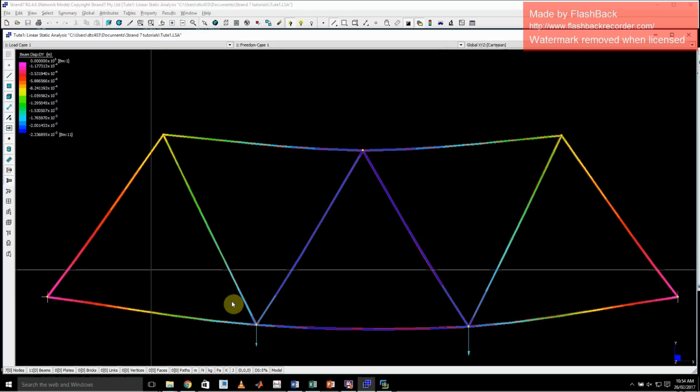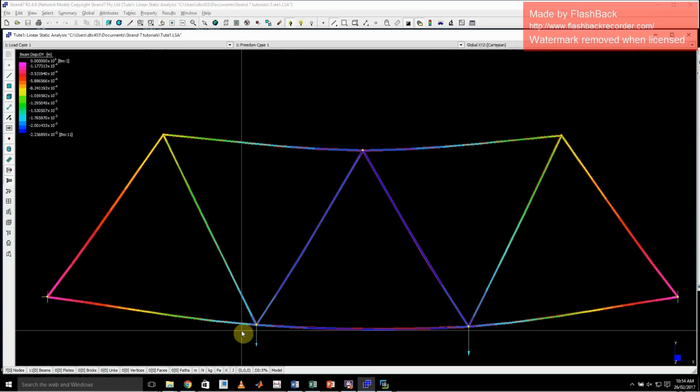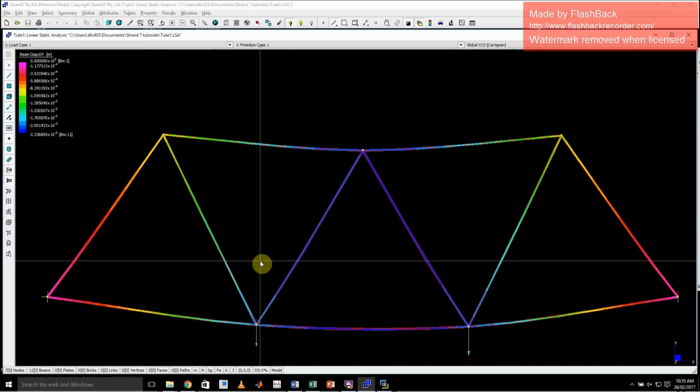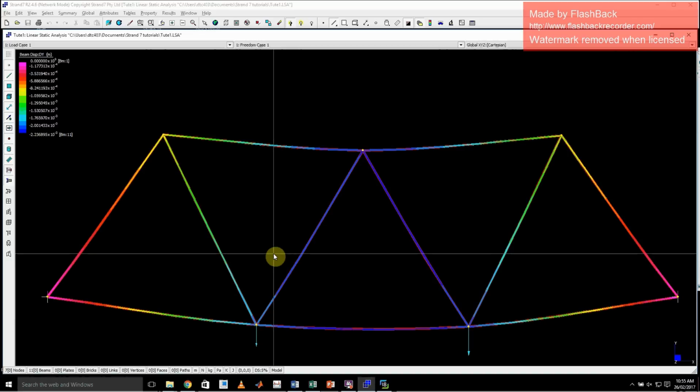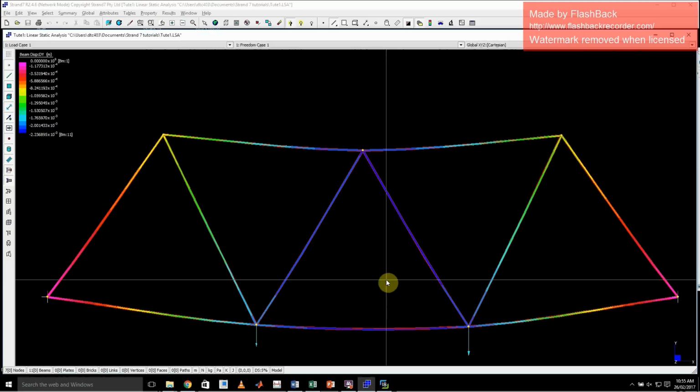So that is not what our bridge would actually look like, but it does allow me to see that yes, it is sagging in the middle the way that it's supposed to. You might want to do this to see how much, say, your water tower is going to deflect, see if you can figure out which beams might be moving, whether you wanted them to or not. But predominantly it's useful to make sure that your whole model was joined together the way that you thought it was, and that it bent the way that you thought it did.